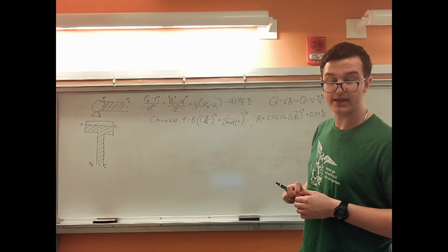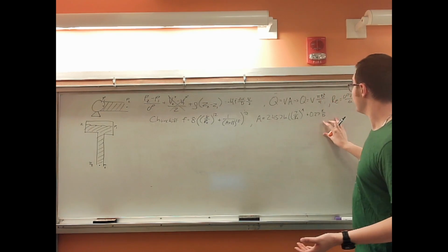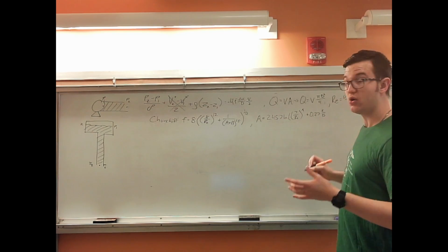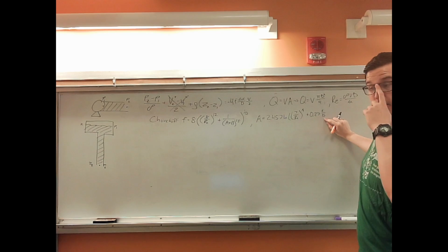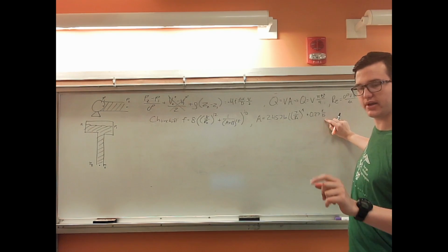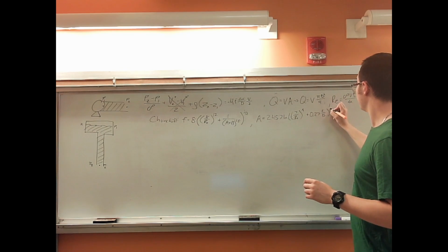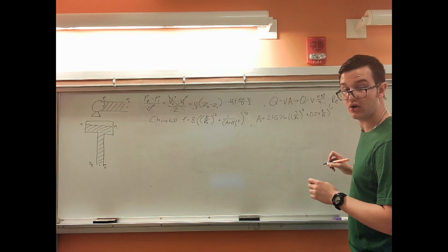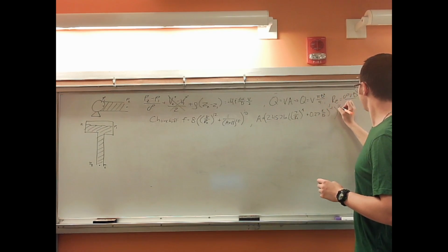This epsilon is the roughness of the pipe, and d is just the diameter. We are going to represent this specific epsilon over d, the roughness divided by the diameter, as its own variable in our code, but we'll get to that later. All of that is to the power of negative 1. And then all of this is to the 16th power.